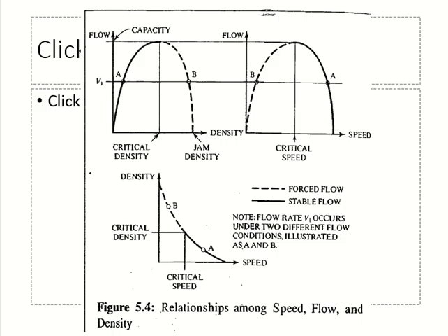So the point at which the graph, instead of going up, starts to go down, the flow, instead of increasing, starts to decrease. This is the point where the density reaches critical. And why is it critical? Because now the flow is decreasing. If you don't pay attention, you are going towards a traffic jam. That's why it's critical. And the flow at which this happens, we call it the capacity.